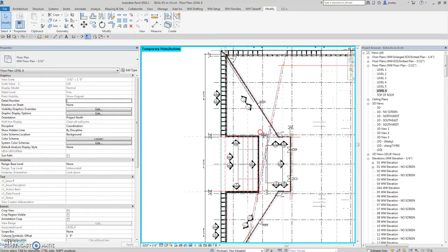Hi, so the problem I had is that these two curtain walls that are sloped, I had to adjust them to just push them out an inch, which slightly changes the angle of the curtain walls. And this is a problem because we already had elevation views made and detail views made and everything placed on the sheets. And the views don't automatically adjust to stay perpendicular or orthogonal with the curtain wall when the curtain wall adjusts. And, as far as I know, there's no way to link those.